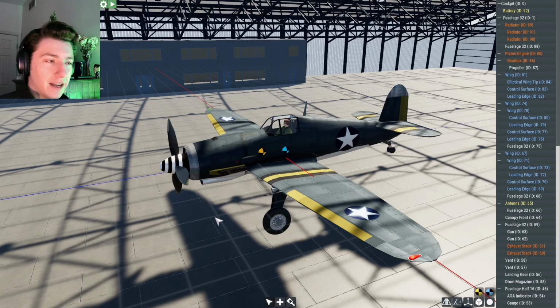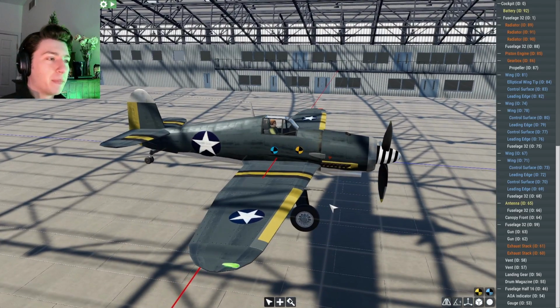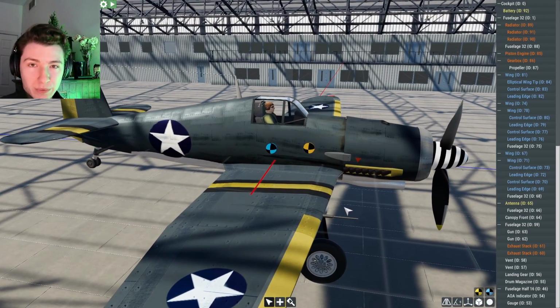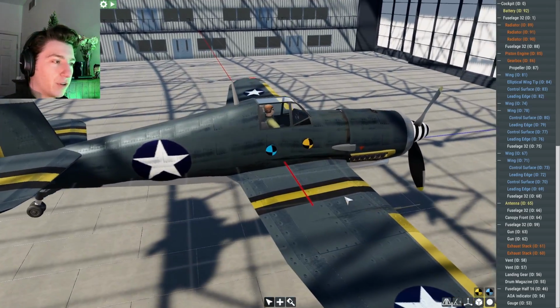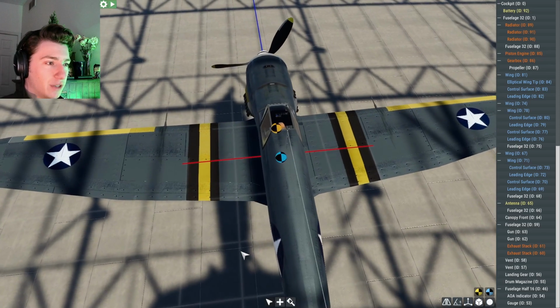So in the last Flyout tutorial video, we discussed how to build your first plane, just something that flies. It doesn't have to be pretty like this, or even good, also like this, but it has to fly. The simplest ways to do that, as we reviewed in the last video, are to build a craft that has a center of pressure, or center of lift as we call it in this application, that is behind the center of gravity, but not too far behind, because if you put it all the way back here, weird stuff happens. And then you need your control surfaces.